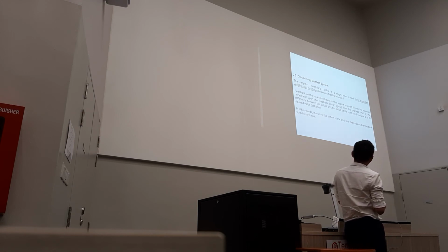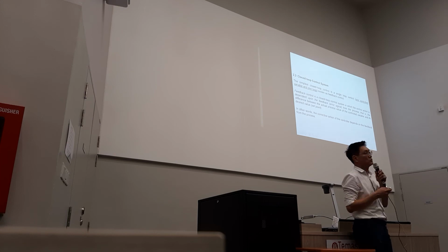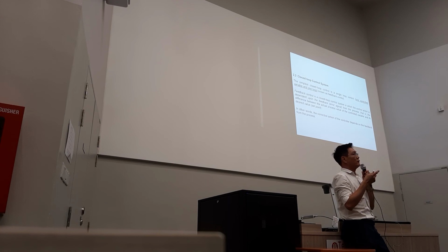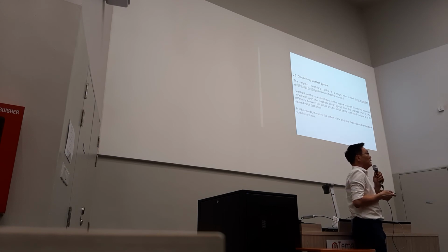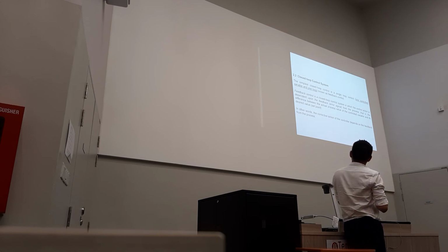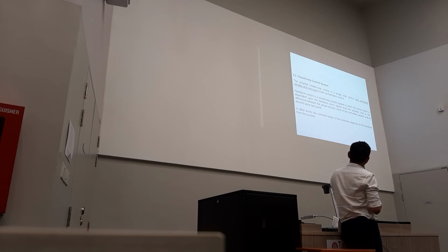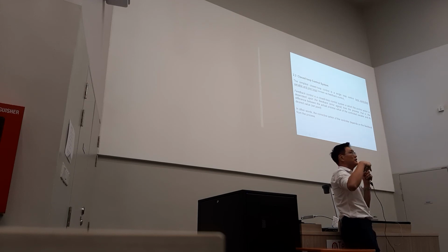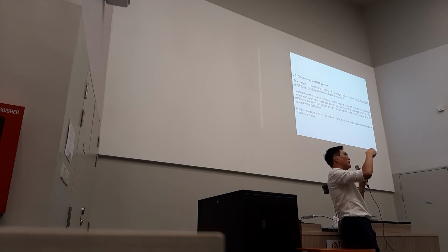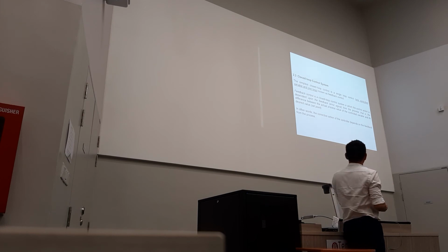So a quick definition of the simple closed loop control. Still remember what closed loop control is, right? We have closed and open. We have feedback and feed forward. The closed loop control is a single loop control known as feedback control. Normally closed loop is feedback. I measure something and then I send it to the controller. The controller will change the final control element and it affects the thing that I measure. That we call feedback control.